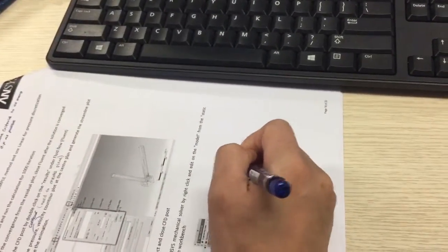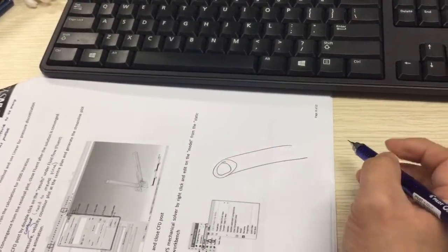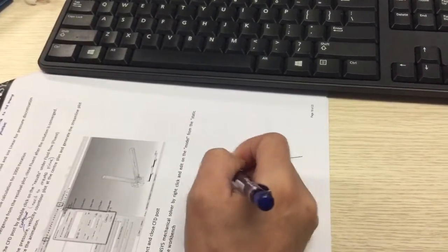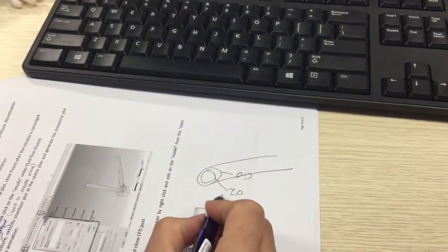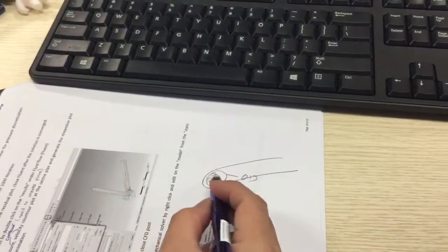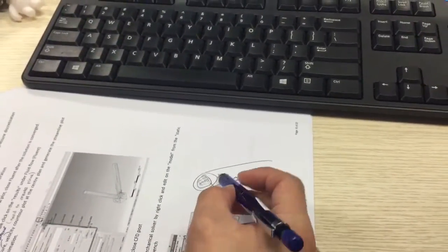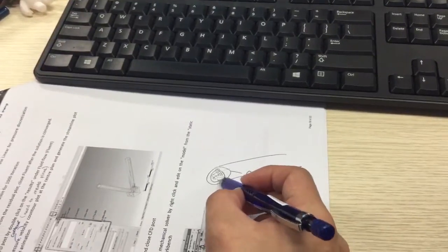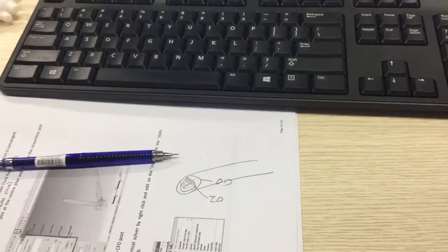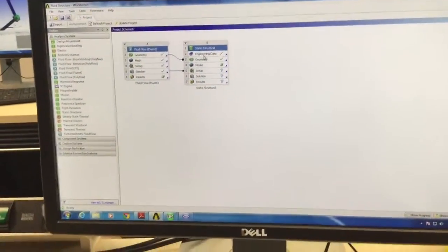you have this kind of structure, right? This is the wall, OD, ID. So what is inside here is actually ID. Correct, it's already ID because you are doing the CFD on the fluid volumes. So this particular volume is for the structural simulations, which is here. Later on we will export the fluid pressures to the structurals.